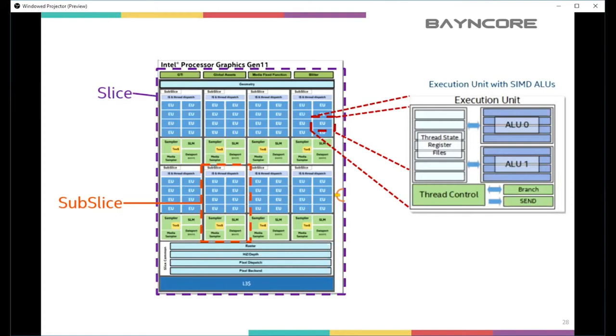And then even with the execution units or the arithmetic logic units, you've got these very wide SIMD registers. So you can have more than one calculation being done in a single cycle. So you can see here that there is nested parallelism within the device itself.